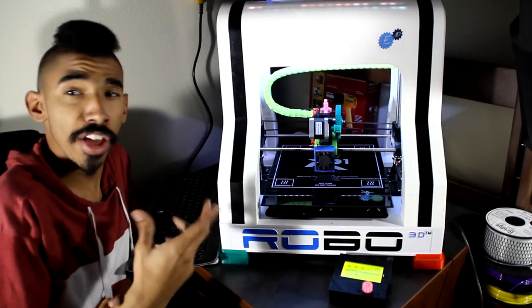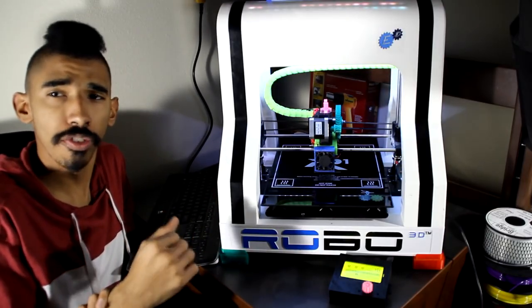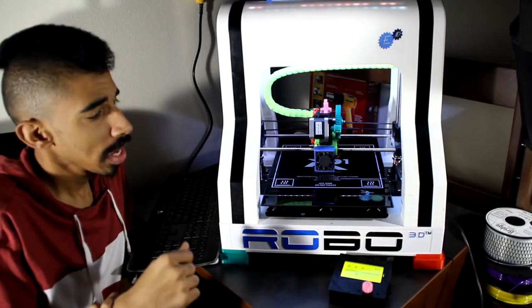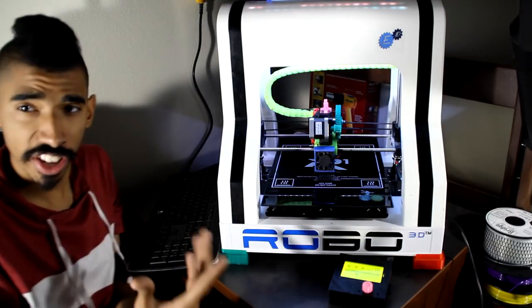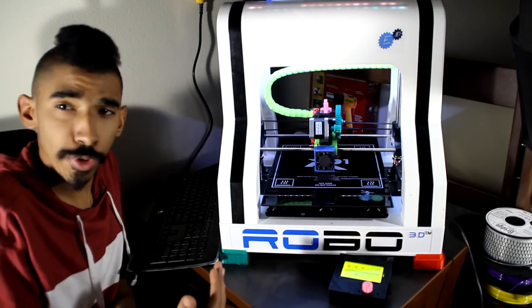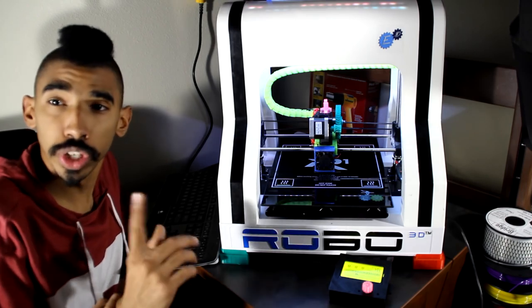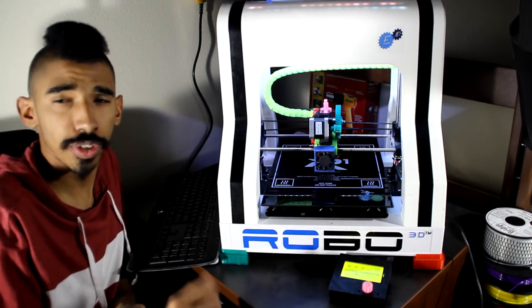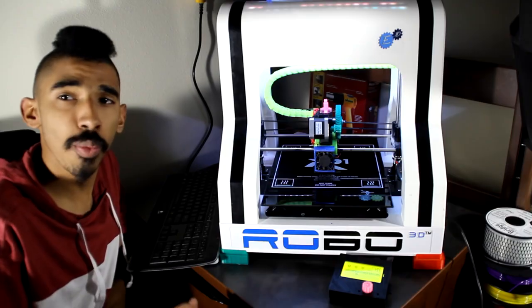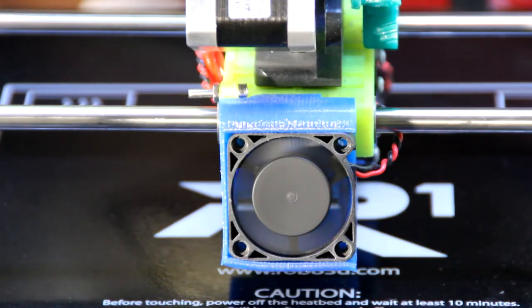So another useful command for temperature is running the fans on and off before or after a print. Before the print starts, if my fans are running, I tell the printer to turn the fans off. And after the print is finished, I make sure to turn the fans on so the extruder can cool down faster. The way you implement this command is M106 and M107. This is an M106, and this is an M107.